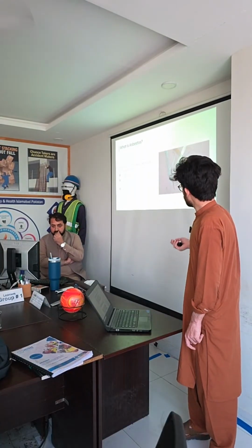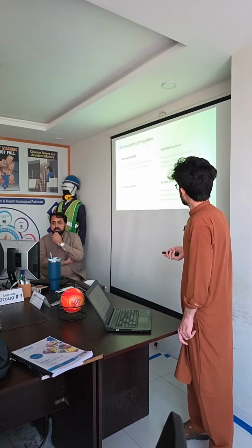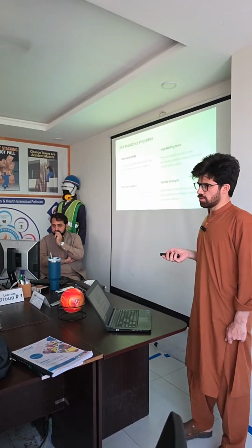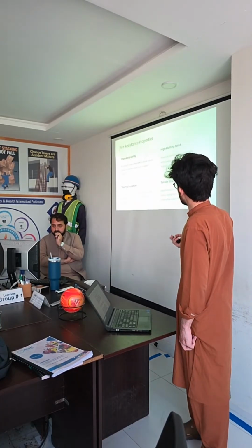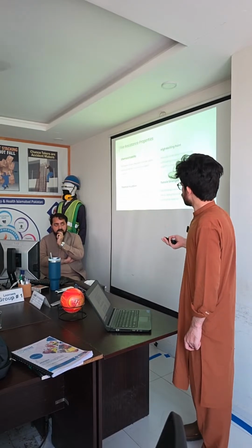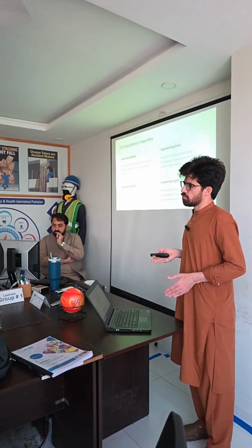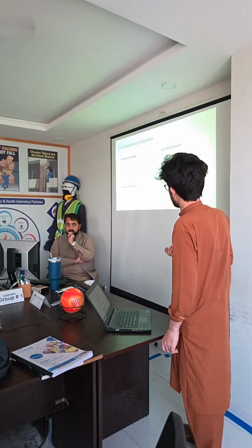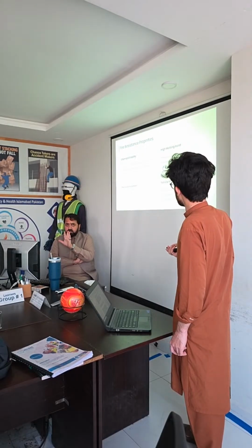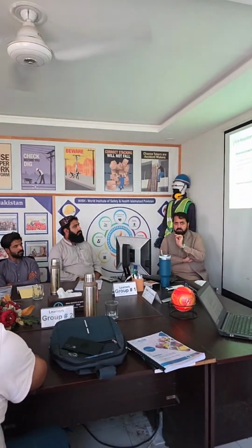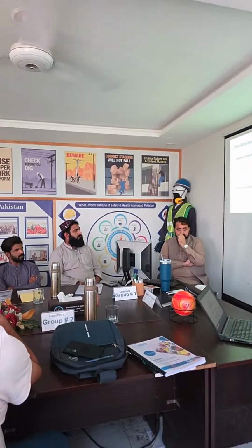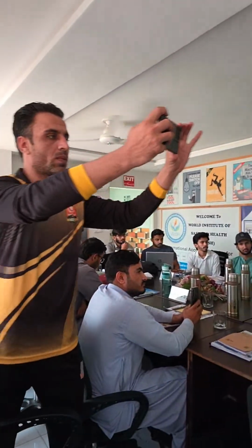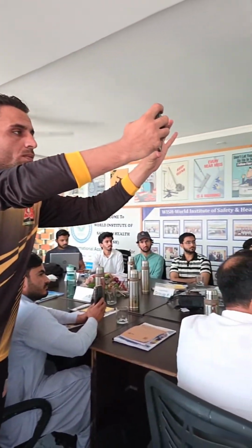So we will go to the next slide. We will discuss the properties of asbestos. Fire resistance properties. It was used because of its high fire resistance. The first one is chemical stability. In inorganic silicates, these minerals do not contain carbon and therefore cannot ignite or support combustion. It has high fire resistance because it doesn't contain carbon in its chemical structure.